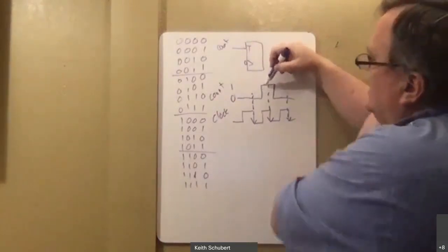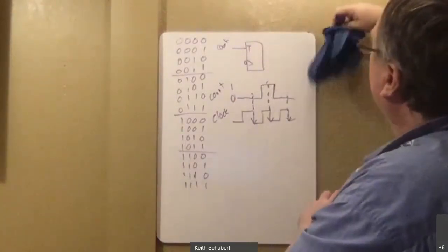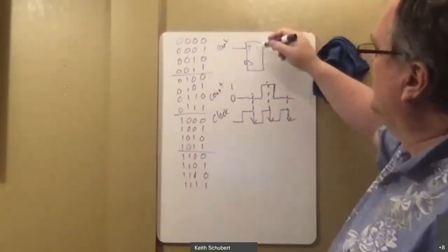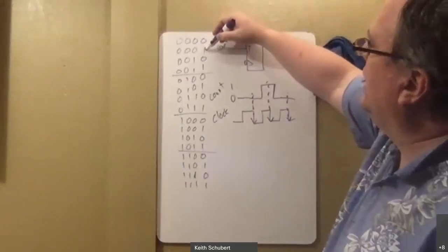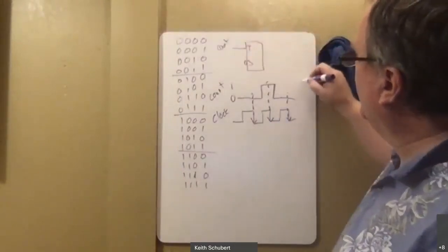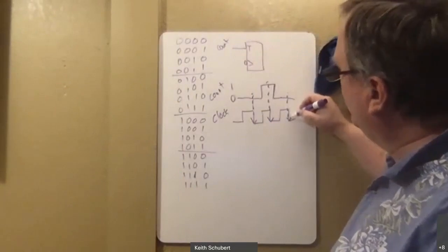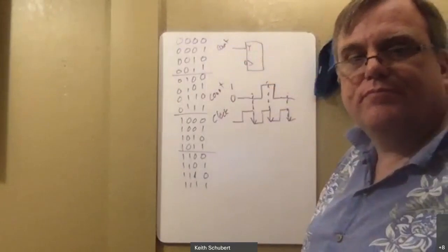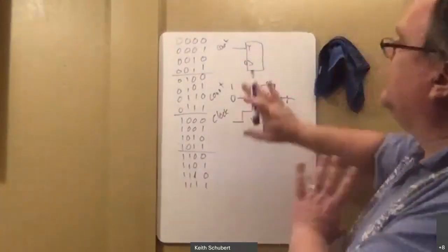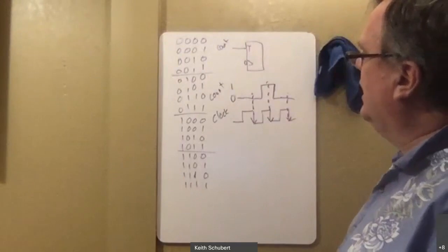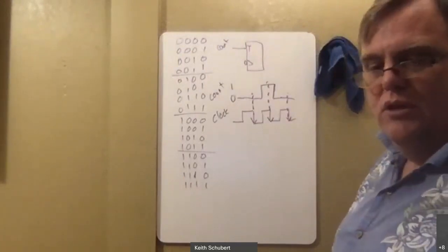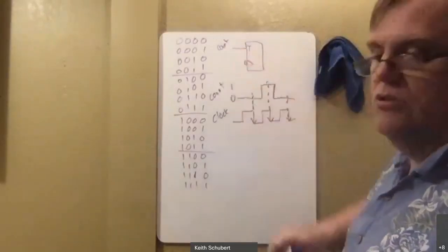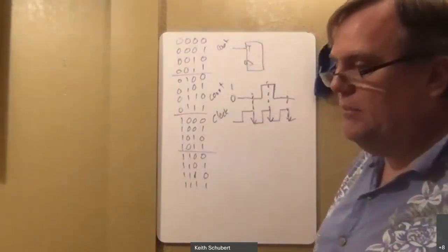So therefore, as long as this is a short pulse that you set up, that count will work perfectly fine. It'll see a count pulse and it'll count. It'll wait a while. Whenever you send it the next count pulse, whenever it's 1, when this is on, it'll do the next transition. So this will still give me that same type of counting pulse behavior. I just have to be careful that I don't make this count hold too long unless I really mean it.